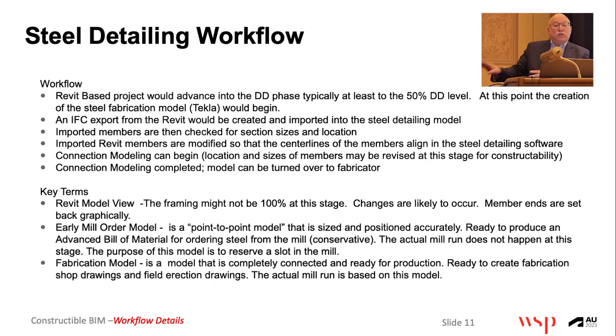That's all sorted out. Those are big deals, because if two members can't come together, you have to change the working point. You change the working point, you change the forces on the member, and you have to re-engineer the member. You don't want to do that in the middle of the shop drawing process. So it's logical to get those things thought through in the design stages.